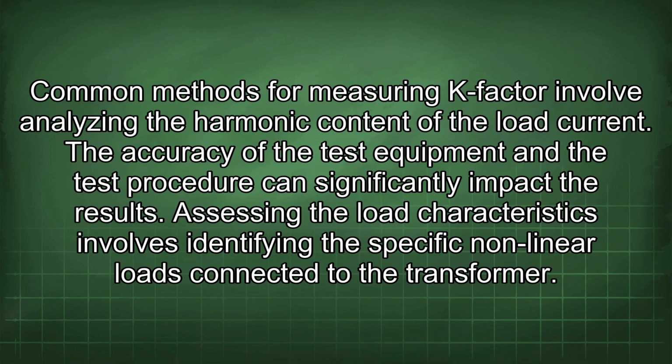Common methods for measuring K-factor involve analyzing the harmonic content of the load current. The accuracy of the test equipment and the test procedure can significantly impact the results. Assessing the load characteristics involves identifying the specific nonlinear loads connected to the transformer.